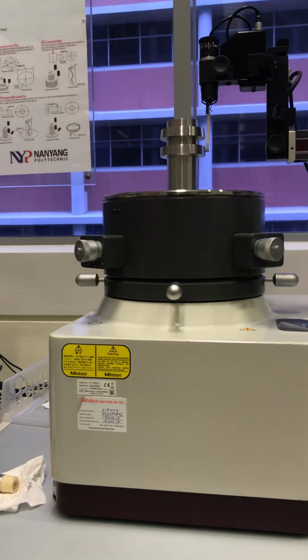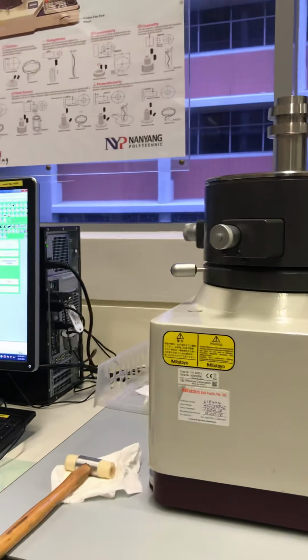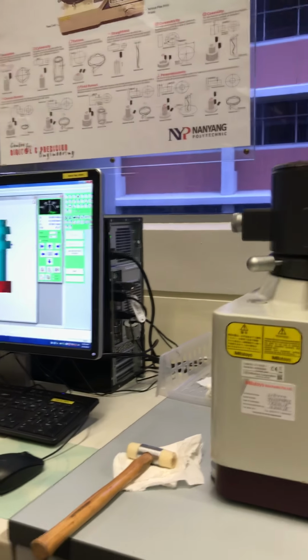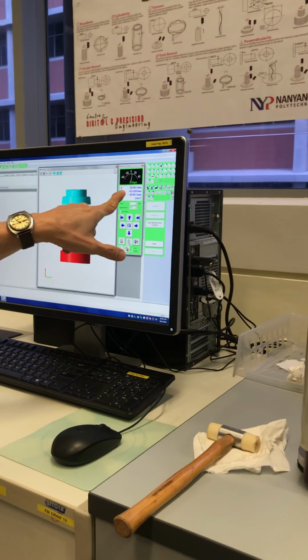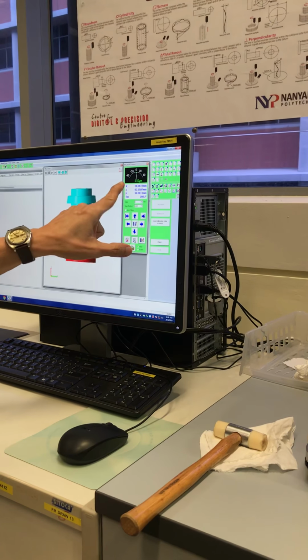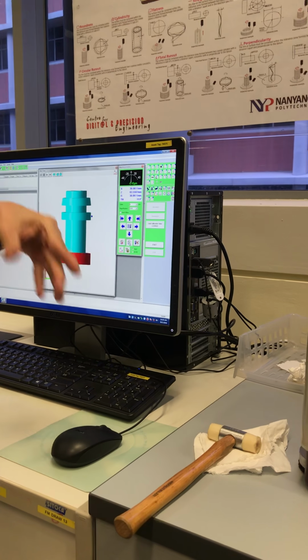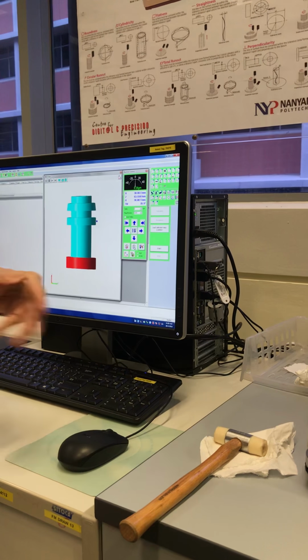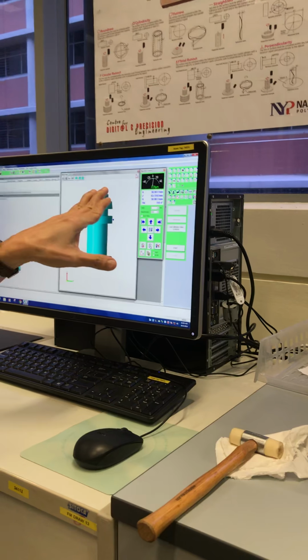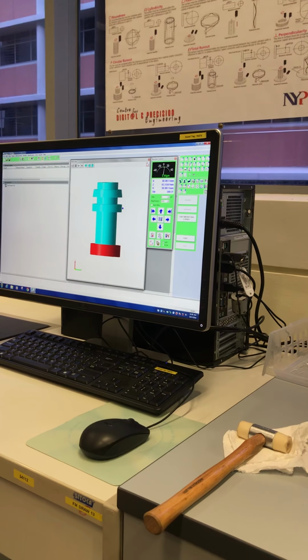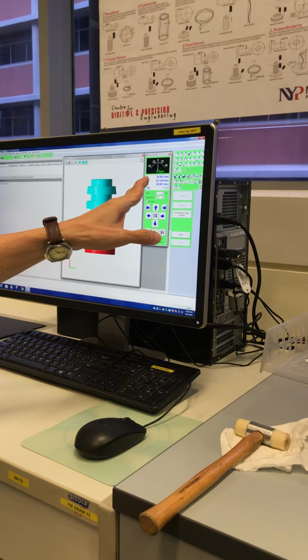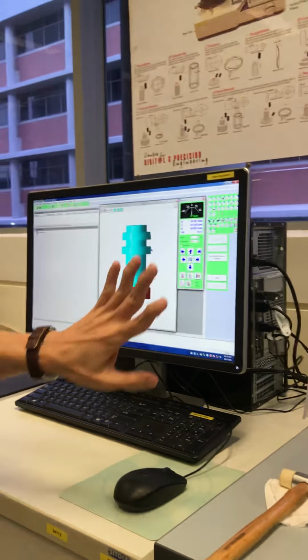But if you think this is no good, then you need to repeat the alignment again, at higher magnification. But for our workpiece, 1000 magnification and an error of plus minus a few micron is good enough.